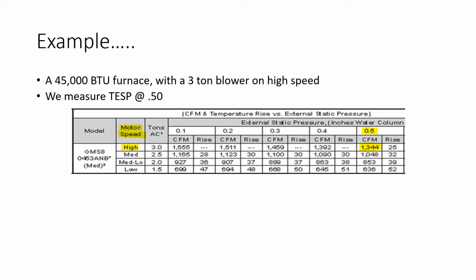Now you'll notice in that previous chart that your return air static would be a negative value, and your supply air static would be a positive value. So these values, as far as above or below atmospheric pressure, are disregarded, because that negative value of the return air is still a force that works against the blower wheel.